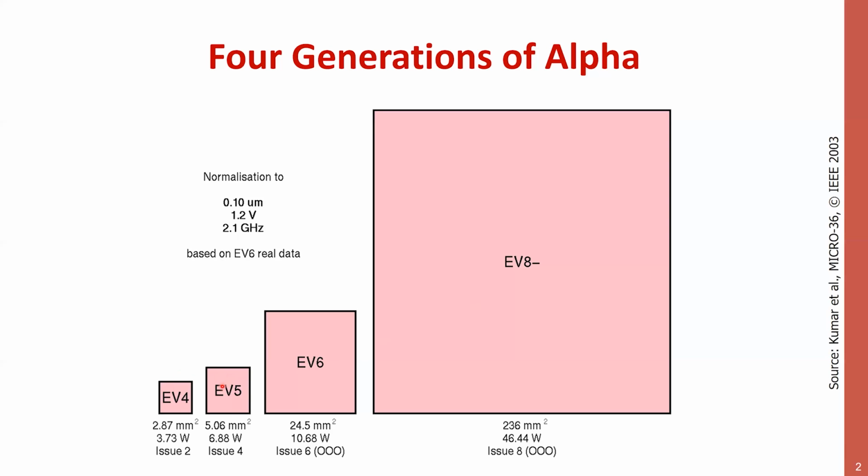These are in order, so the scheduling is relatively simple. It's just a question of checking dependencies, and here we have out of order, so we start putting reorder buffers. Here we have reorder buffers and reservation stations, but since issue width goes up, probably the size of these reorder buffers goes up quadratically, so it's much bigger, and so on and so forth. Okay, so this is one thing that is maybe astonishing if you look at it well, right? The number of transistors, the area, went up very dramatically in general purpose computing.